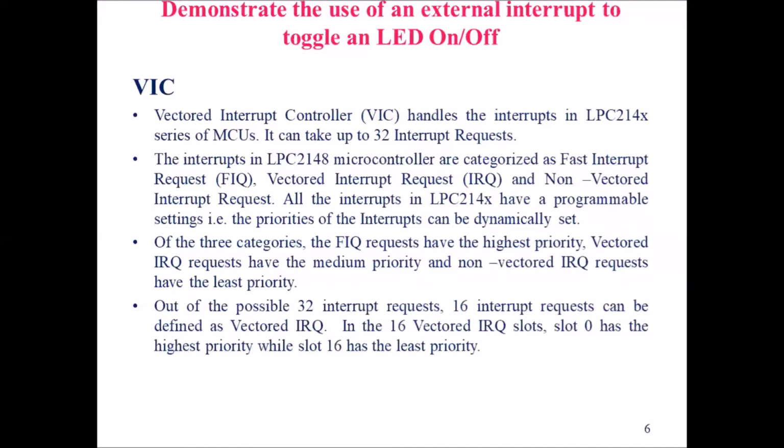In the fourth program, we mainly concentrate on the vector interrupt controller or vector interrupt request. How many vector interrupt requests can be handled in the LPC2148 microcontroller? Up to 16 interrupt requests can be handled. In the 16 vector interrupt request slots, slot 0 has the highest priority, while slot 15, that is n minus 1, right, has the least priority. So this is all about the vector interrupt controller.